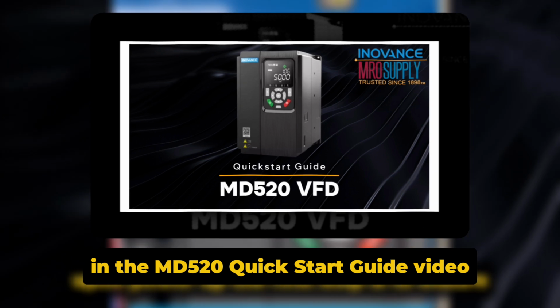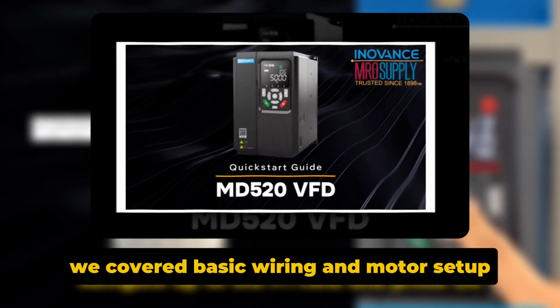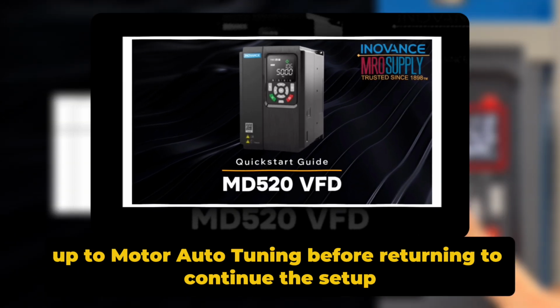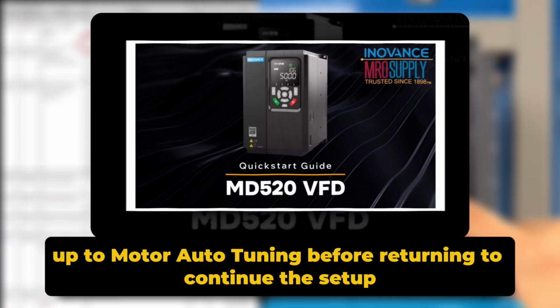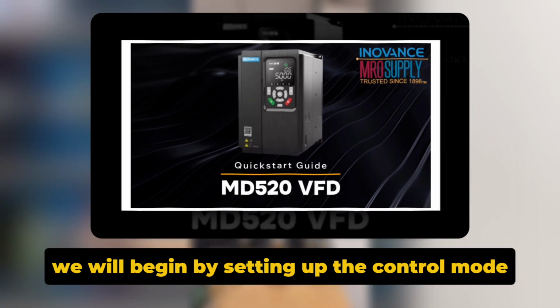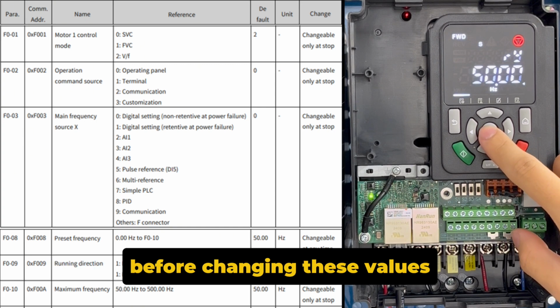In the MD520 Quick Start Guide video, we covered basic wiring and motor setup. Please review that video up to motor auto tuning before returning to continue the setup. Once you have completed those steps, we will begin by setting up the control mode. Please ensure that the motor is fully stopped before changing these values.